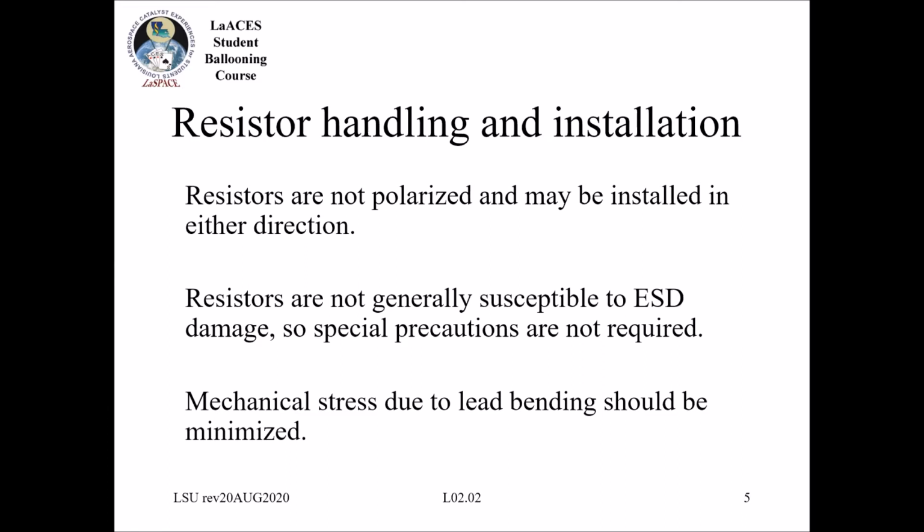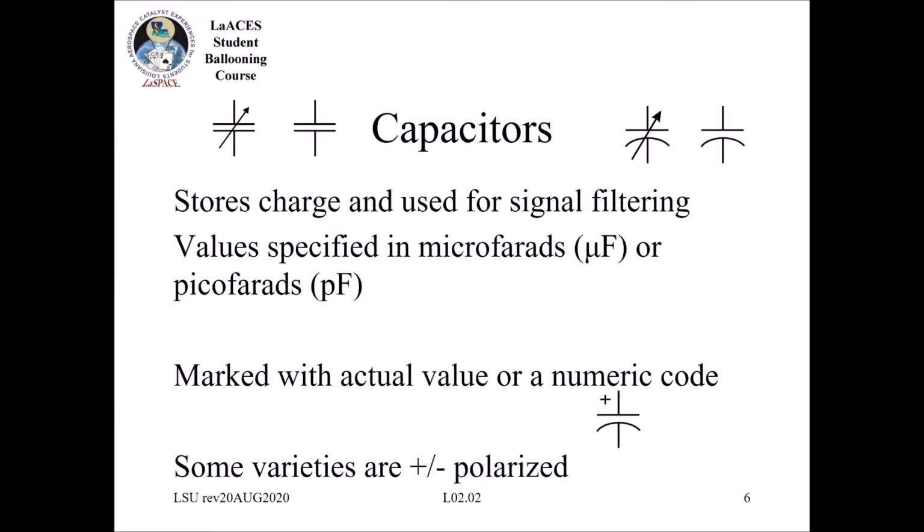The biggest concern with them typically is the mechanical stress due to lead bending. If you keep inserting it into your circuit and you're like, that's not right, and then you bend the leads multiple times, eventually the leads will crack. So just be aware of that. It's always great to have a test set of resistors you might insert, and then whenever you want to permanently insert them, I would just get a new one because they're super cheap. And normally you'll have like 100 of them if you order them from DigiKey or something.